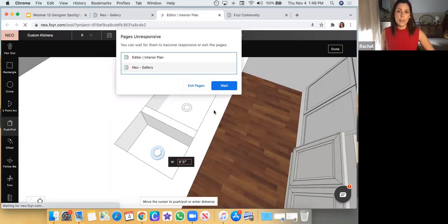Janine says, I'm still having problems getting free movement with grouped objects. I made sure to put an object into free mode before grouping, then click away. So the answer, Janine, is that right now, once objects are grouped, you cannot move them in free movement, but that is changing. When you group products, you can only move them side to side, up and down, or back and forth. You don't have the option to resize or rotate in all directions. But the software as a whole is getting several new features added in the next few weeks, and that's one of them.